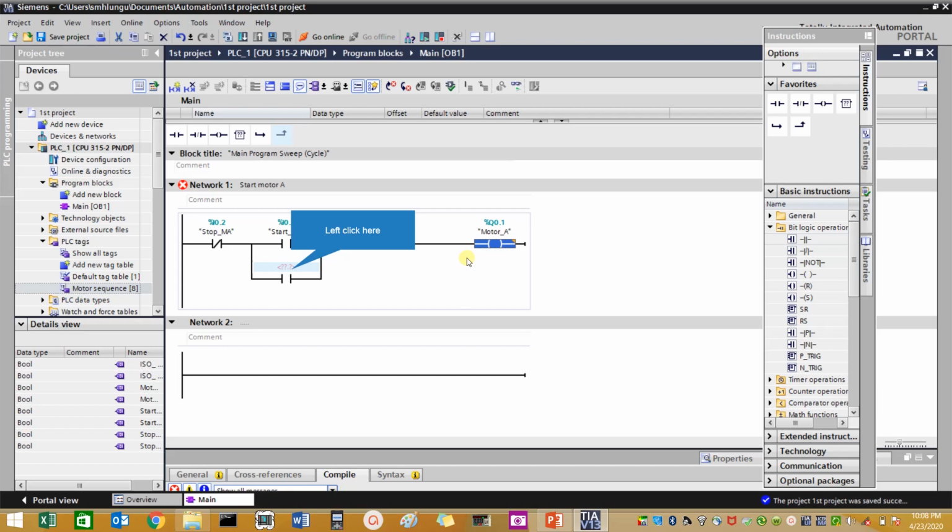Are you with me? So that when the motor is running, this branch will be active, retaining power there. But this is a push button. A push button is spring-loaded. So when you press that button, power will flow, current will flow. As soon as you remove your finger, there is no current. So you need to latch that branch, that circuit. Okay, as you can see there.